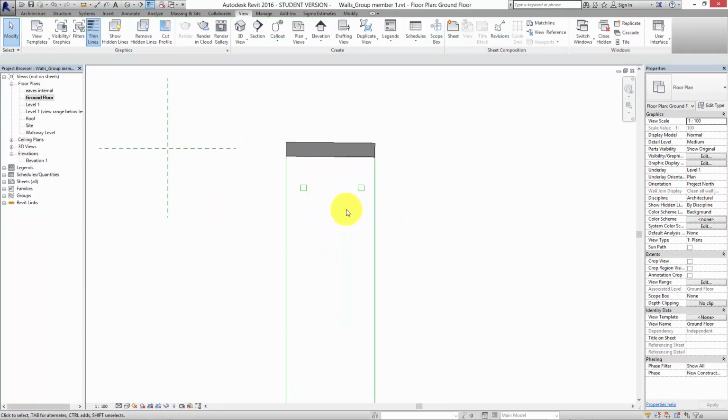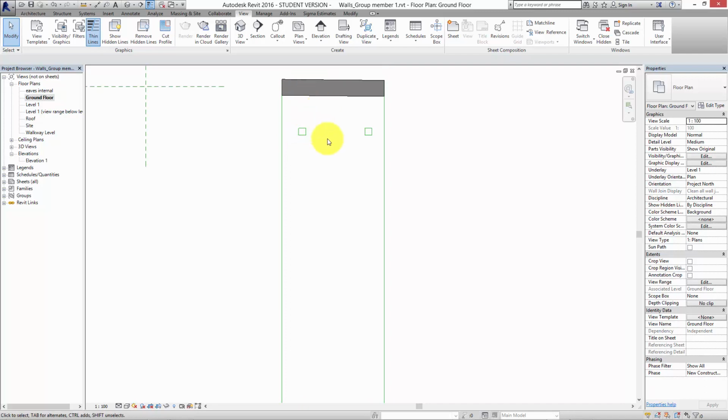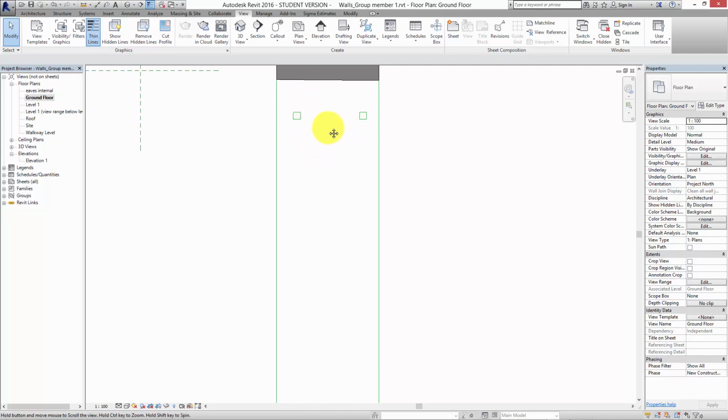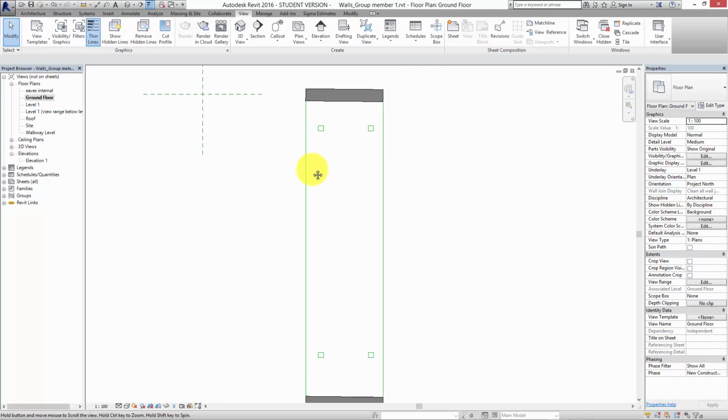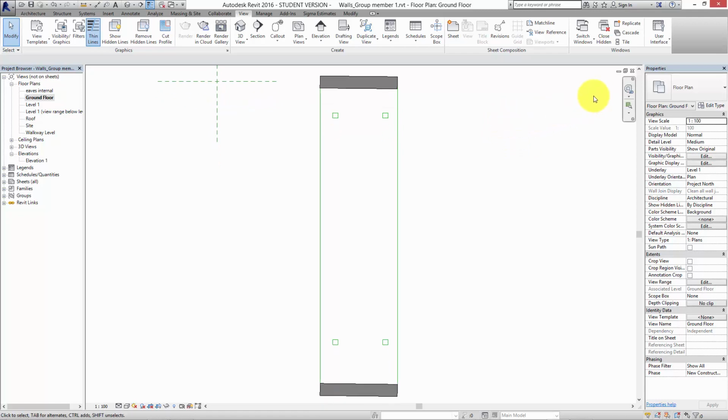So here we have something that's actually common among everybody who's working on it. We have a position of the walls and we have a position of the columns, and the easy way to control all these things without having to do everything individually is to set up a grid, like we did last semester. But you don't want to set up the grid in the structural model. You should set it up again in the group model. So you often have to go back and modify the group model to add things that everybody can use as reference points.